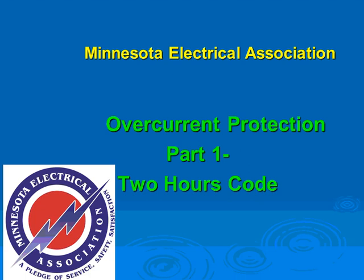There's also the handbook for electrical safety. Jeff teaches 70E and I teach 70E. When we do 70E, it tells you what type of PPE you need to work safely on electrical equipment. That's directly tied to the size and settings of the overcurrent protection device, so it's a big deal. And of course 70E, you're familiar with arc flash, arc blast, and shock hazard that can come from any power system.